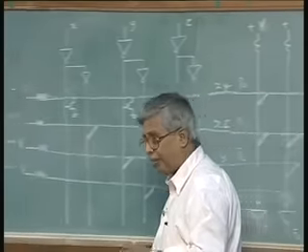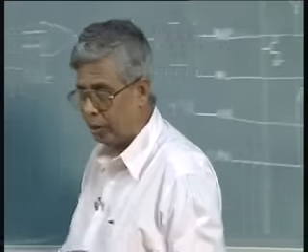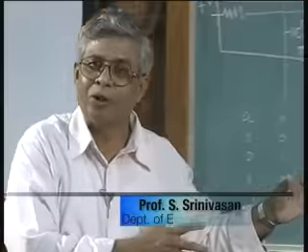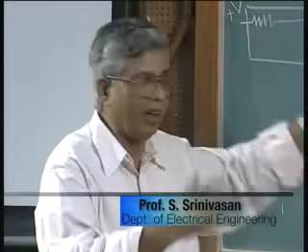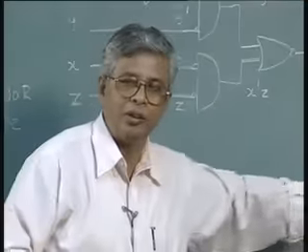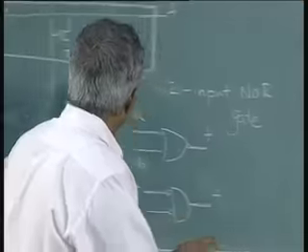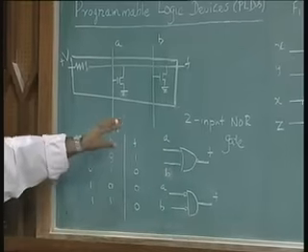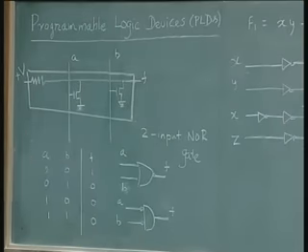This is not hardware. As I said, I am not going to talk too much about the implementation technology aspects for programmable logic devices, but this is a circuit technique we are using, because I am given a function of AND OR inverter and asked to implement it using NOR gates. I need to have this type of circuit technique. So, the circuit technique of converting the AND OR inverter into a NOR logic family is what I wanted to explain to you using this technique. This is the design using programmable logic array.